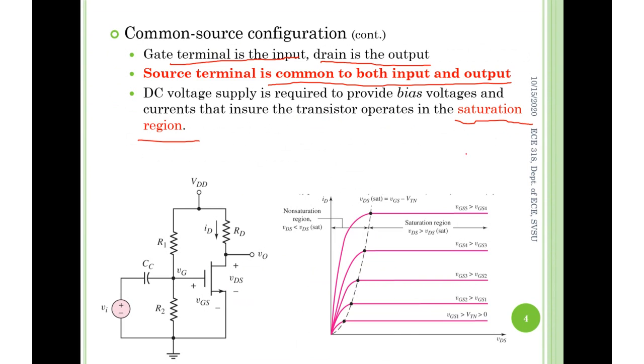Does it make sense? This is the saturation region, blue point here, amplifier. This is the non-saturation region. The Q point is here, it's a switch. If you fall down here into the cutoff region, well, it's off. You're going to do nothing.